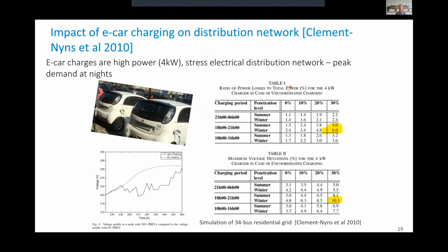Here the power loss is excessive because the grid is weak. One way that a weak grid manifests itself is in voltage problems. The voltage might drop, which is seen on this curve here. But also the current on the line may become excessive, which will first translate into power losses. When you start losing 5 or 6% of the power, you're losing 5 or 6% of the money. But that may also cause heating of insulators and transformers that eventually might cause a disconnect.